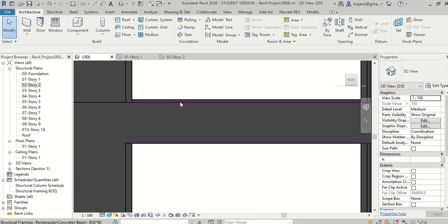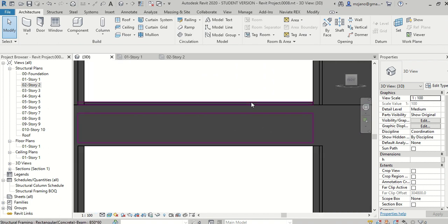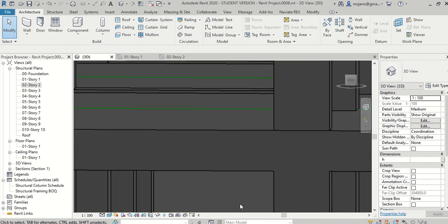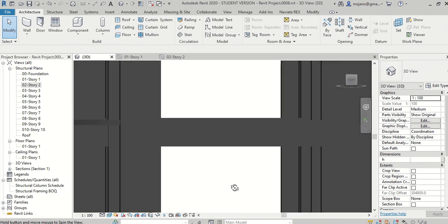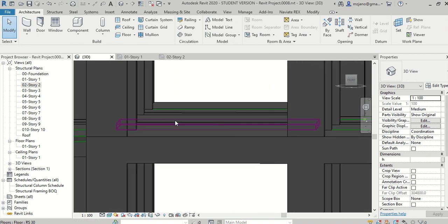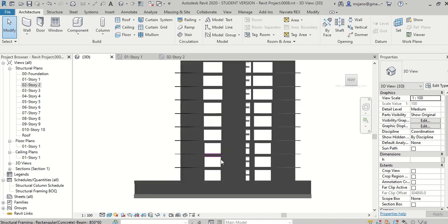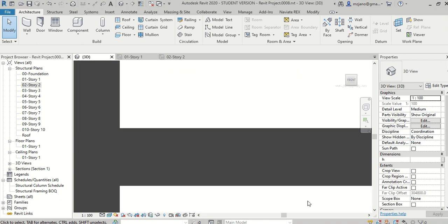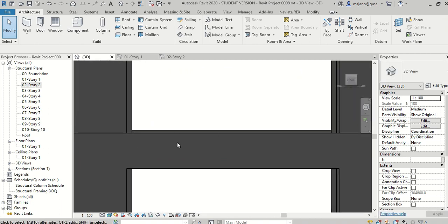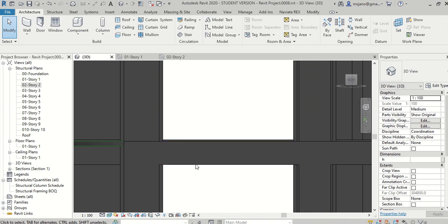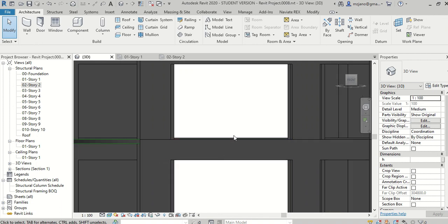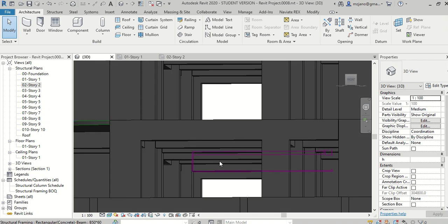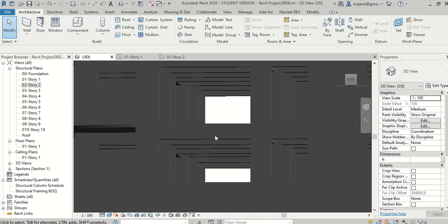You can see these 10 centimeters from above, so the thickness is increased from the top of the beams, not from the bottom. So you can see these 10 centimeters for the beam behind this beam. So the view will be different if these beams have different sizes or depths.